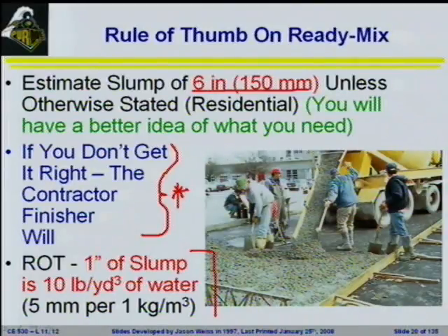What about if there's a maximum water-to-cement ratio? Would it be acceptable to add water on site then, say if you do initial testing and you come out below it? There are some criteria on when you can officially add water on site, and I will cover those later on. You can do it, provided there are about 6 caveats, like you can't exceed the maximum water-cement ratio. There are actually people who design the concrete and hold water back so that they can do that on the site, so that the contractors are happy.